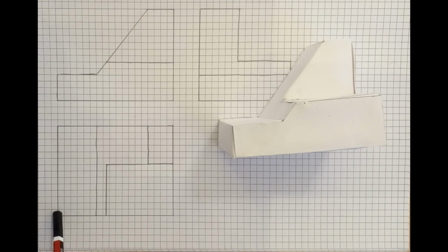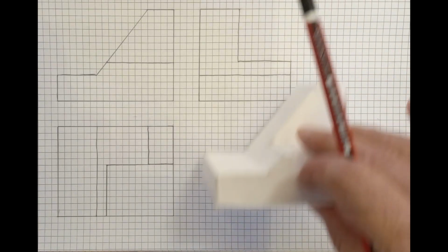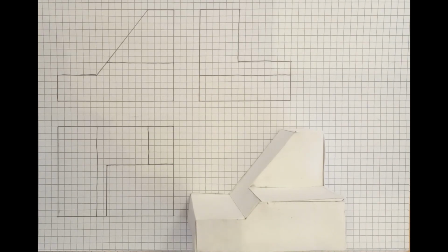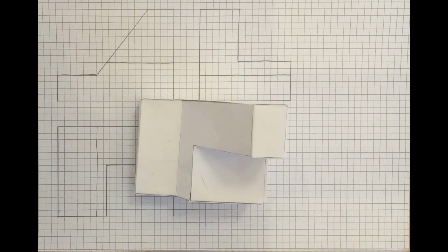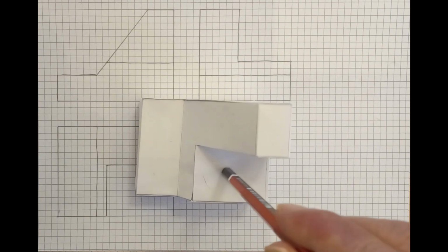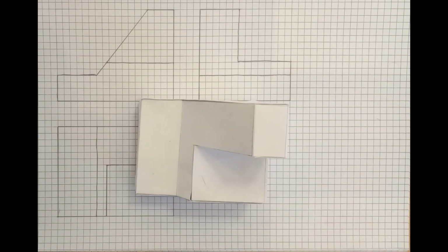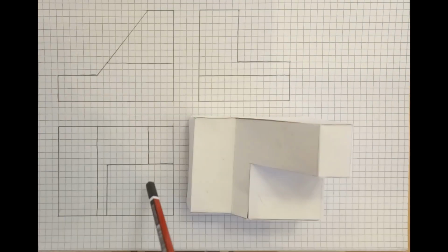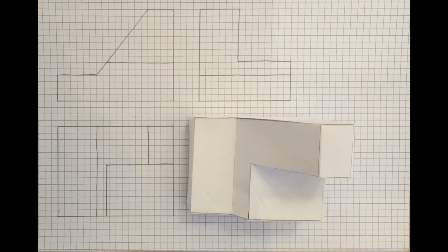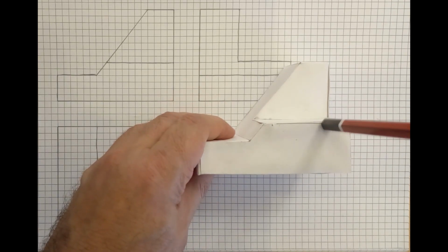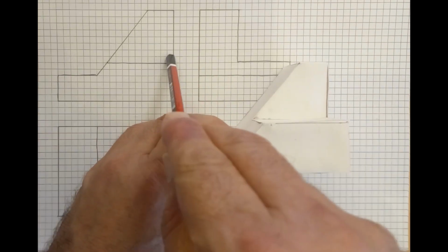In the top view, it will appear as a line, this line, and in the side view, it will appear as a line as well, this line. Another surface, this surface, is horizontal, so my side will be perpendicular to it in the top view, if I'm looking from the top. So in the top view, it will appear as a rectangle with its true dimension. In the front view, my side is parallel to this surface, so it will appear as a line, this line.